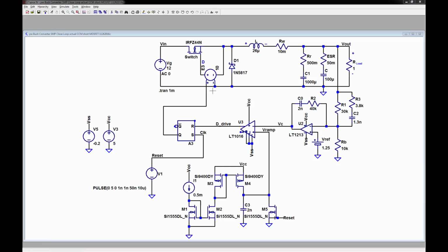So what I want here is I just do a voltage controlled voltage source, and that voltage controlled voltage source will then isolate this between here and here. So if I have 5 volts here, I'll have 50 volts here because it's 10 to 1. So I may want to scale that down because I might not want 50 volts on my gate to source. But we'll sim it and we'll see what we get, and then we'll change some stuff.